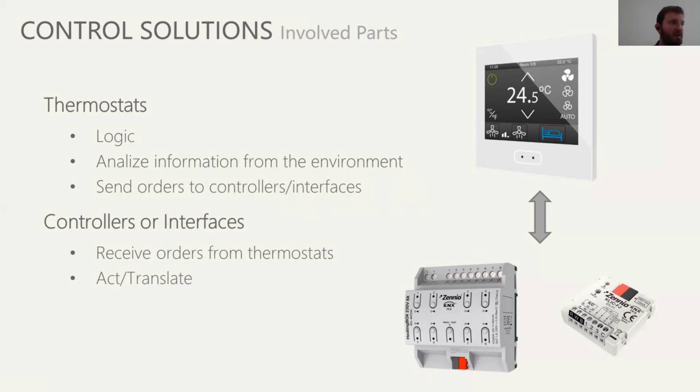For example, it's useful to have them in the manifold, where you can install the heating box in or near the manifold, and the thermostat logic would be there. And in case you change your user interfaces, you can still have that thermostat logic running in the manifold. So it's very useful to treat thermostats as completely independent logic blocks in the KNX industry.